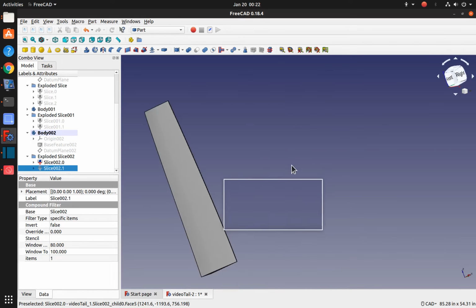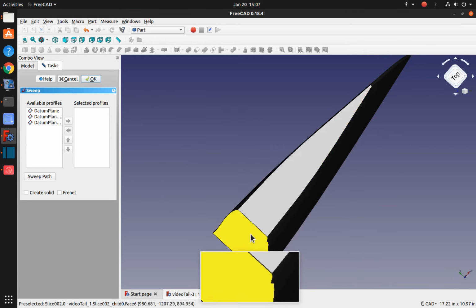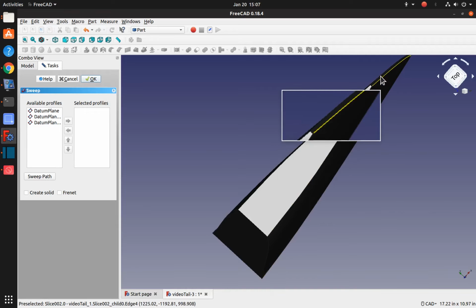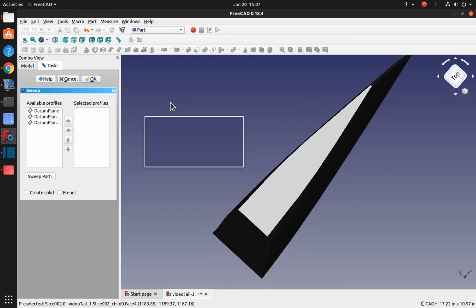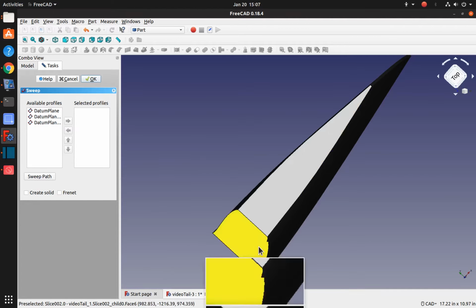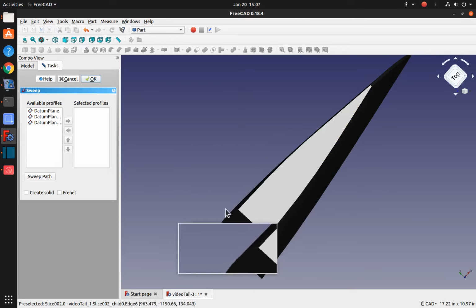I have the rudder oriented now, so we're looking at the top, looking down on it. So this is the hinge line. Here's the top, here's the trailing edge. What we need to do now is make the nose. And as we said in our design video, we want to make the nose elliptical. So somehow we have to attach an elliptical nose to this front.